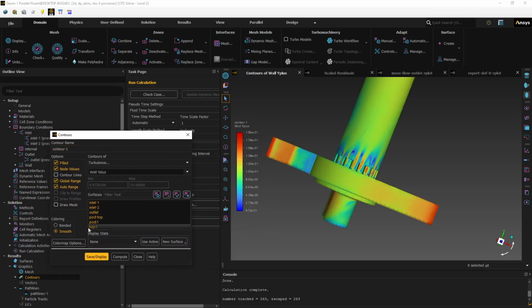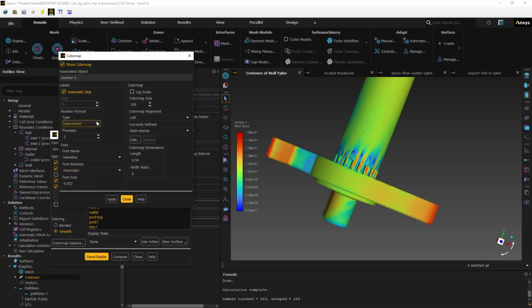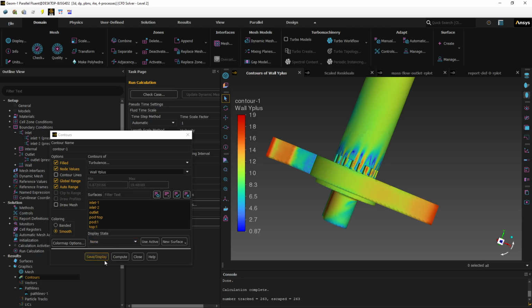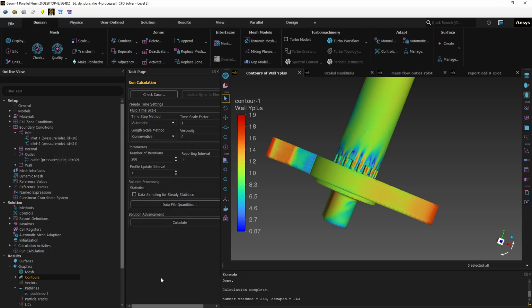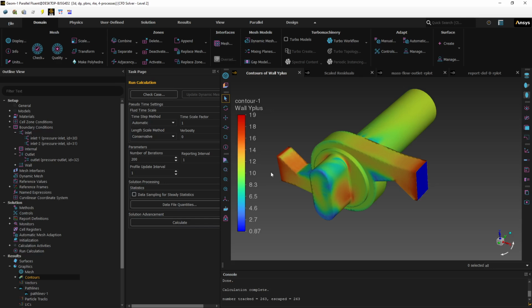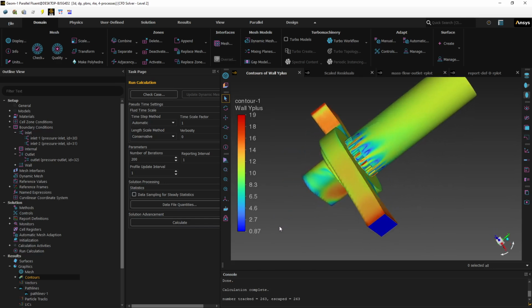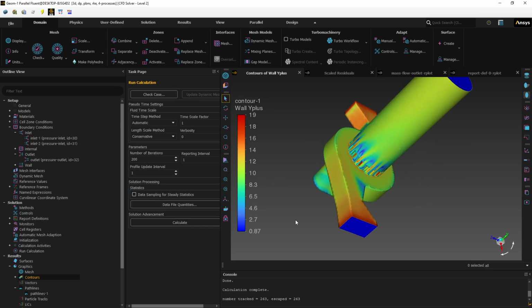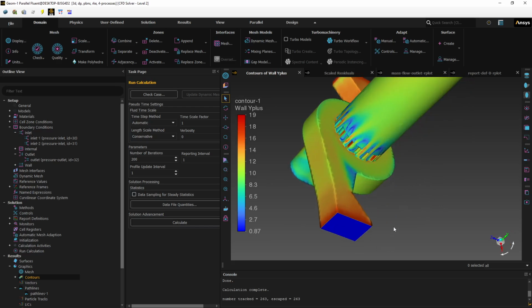And again, with the color map options, let's get rid of the exponential formatting and bump up the length a bit more. So we got a yplus around 19, wanting to get above 11 and potentially as high as 30. So it looks like I can increase the cell height of the first cell some more from the one we had.